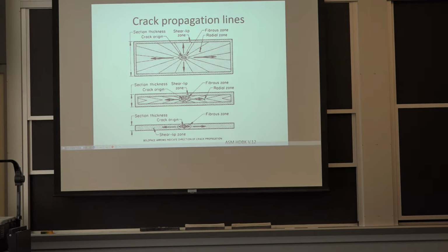We can't analyze them very much. This is being worn out after the fact. That's why you have the lip here. And there was a question earlier about the lip. In this case, you don't really have a lip. You have a zone of final fracture. It's just very, very small, which means the day it failed, there wasn't anything special with the loading. It was a normal load, but it's just the entire history that caused this to happen.